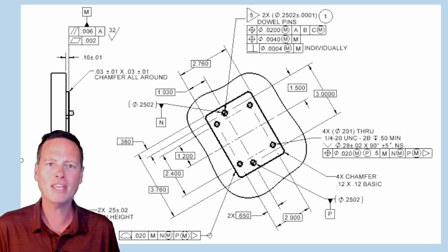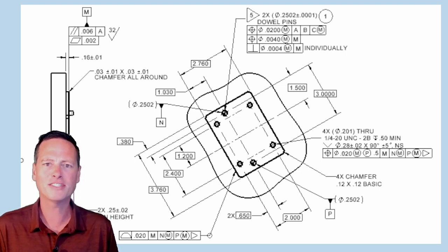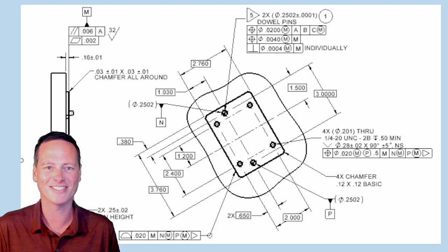Because the datum P pin doesn't move. It's stuck firmly in the machined aluminum piece. But it's not really the pin that translates. It's the datum simulator that translates.